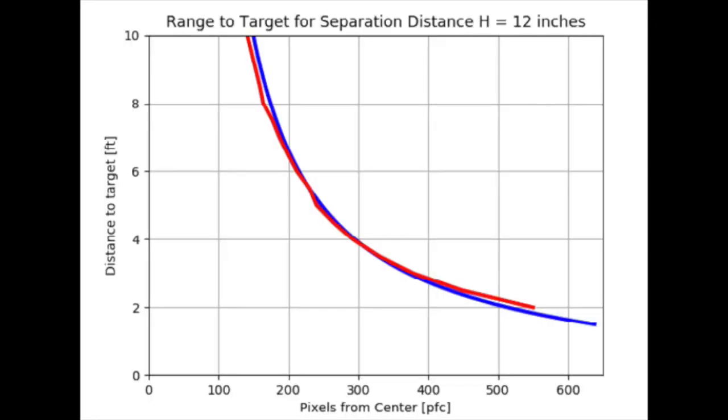Now, to aid the computer vision of this red line laser point, we provide a hue saturation value that turns the whole image into black and white relatively and really exposes that red line laser point. With a theoretical curve in blue and our experimental data in red, you can see that our data matches up fairly well. I noticed that around the 4 to 5 feet region it matches up really well, so I know that when I go to take my data in the future, I want to stay within that 4 to 5 foot